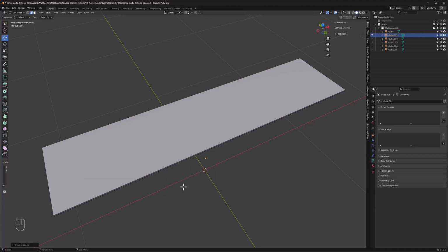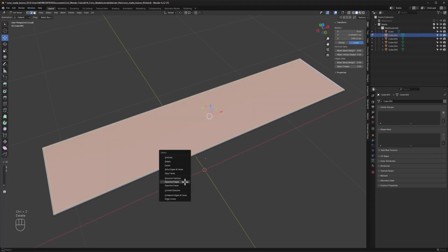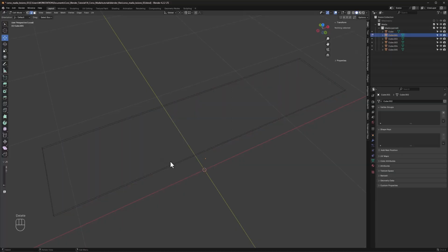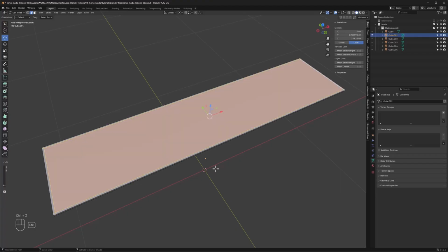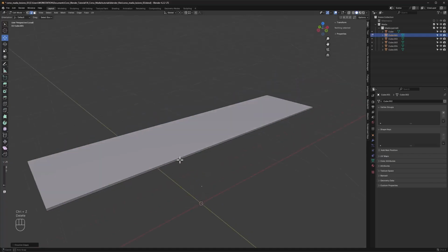Let's go back for a moment and repeat the loop cut deletion step, this time selecting the Edges option. As we can see, by completely removing the edges with this command, we get an undesired result, since the connected faces are deleted, creating a gap in the model. Let's restore the correct modification and reposition the view from underneath the panel.